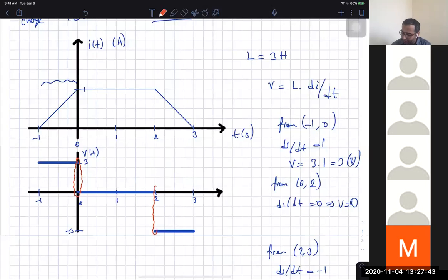In an inductance, although you cannot change the current instantly, you can change the voltage instantly. Basically, those instant terms are a little bit vague, but you should theoretically understand the difference between the instant change in current and non-availability of an instant change in current. But you will be observing an instant change in the voltage, right? This is something I really want you to focus on for now.